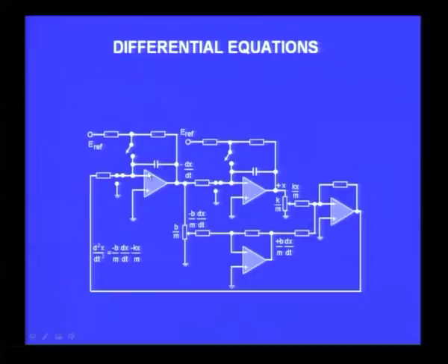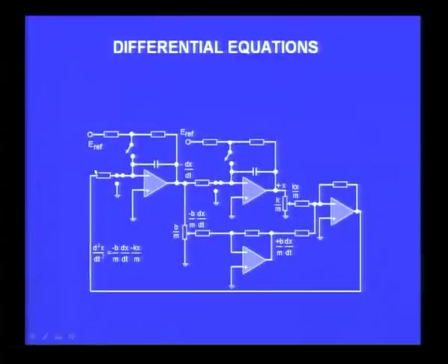integrators. Integrators are much simpler to work with than differentiators. I already mentioned to you, you may get into problems of noise when you introduce a differentiator. Therefore, it is always preferred to use the integrator. So, you use an integrator, assume that d square x by dt square is available at the input, then you can integrate it to get dx by dt at the output. You again integrate it using this circuit and you get x.